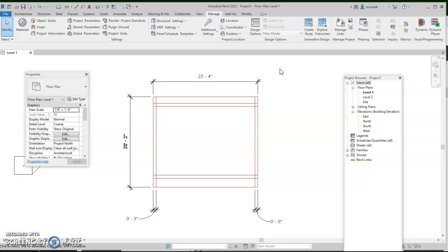Now I would like to actually go through this and draw my dark lines on top of it for my basic walls. I would like to draw with very thick line representing my walls that I'm actually cutting through. In this floor plan, I am cutting through the 2 walls, which I'm going to call wing walls, and these 2 inner walls, I'm going to dark line. Watch how I dark line, because thick lines never cross each other in drawing, in drafting a floor plan.